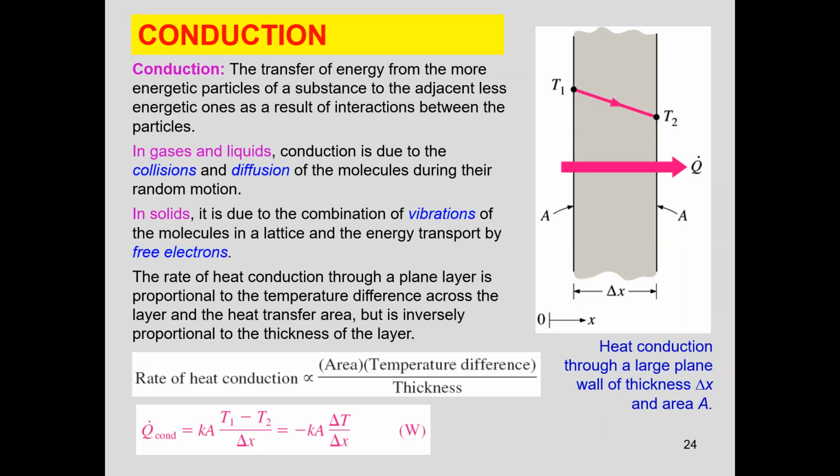The part we have in the syllabus now is basically conduction. Conduction is the transfer of energy from the more energetic particles of a substance to the adjacent, less energetic ones as a result of interaction between the particles. In gases and liquids, the conduction is due to the collision and diffusion of molecules during the random motion. In solids, it is due to the combination of vibrations of the molecules in a lattice and energy transport by free electrons.